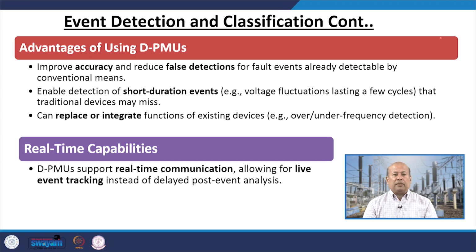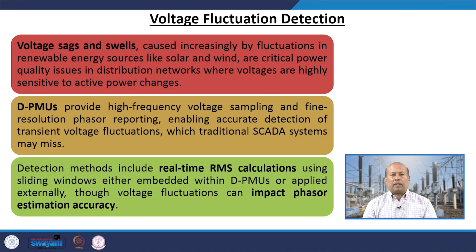Can replace or integrate functions of existing devices, example over or under frequency detection. Now, D-PMUs support real-time communication, allowing for live event tracking instead of delayed post-event analysis.